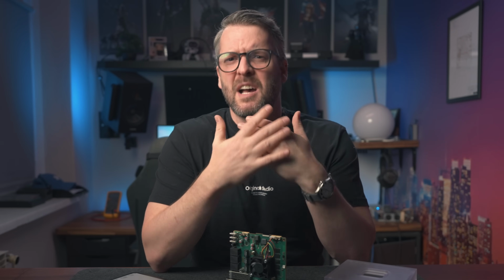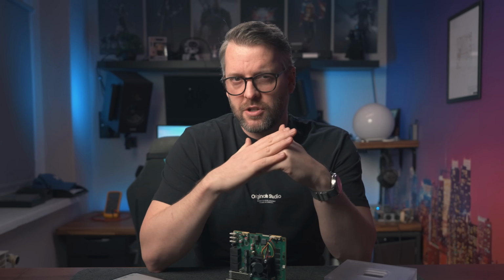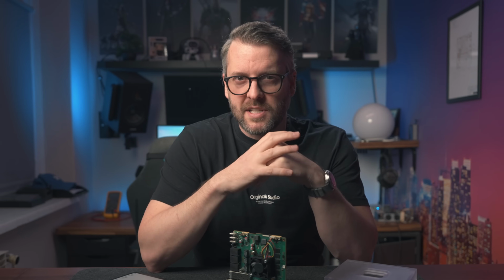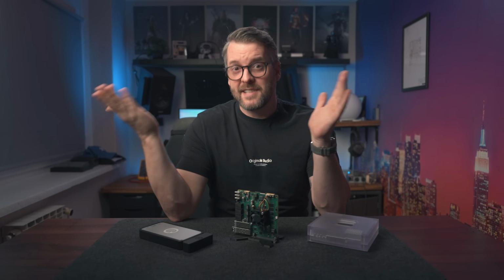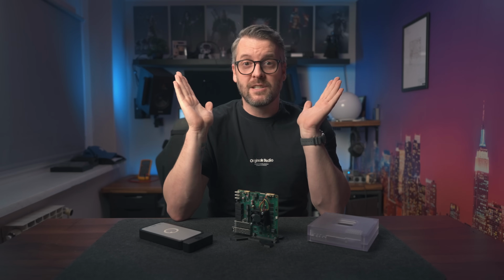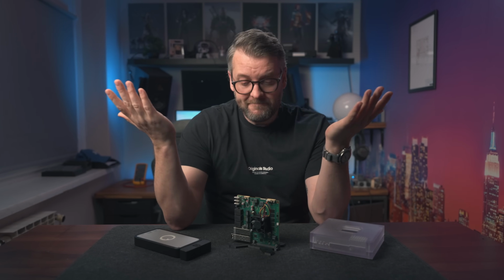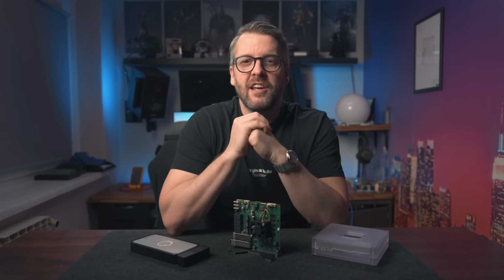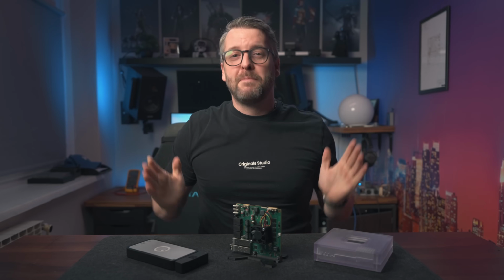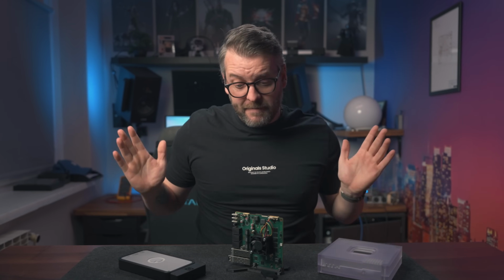But when the CPU is booting up, and keep in mind this is my assumption at this point because it's not actually documented anywhere, I suspect the controller at that point does care about the organization of the drawers in the rack or how the bits are wired to the CPU. And in case it finds anything, it sets this calibration error bit with zero explanation as to where the issue might be. And as to why this behavior is not documented anywhere, ask NXP. We certainly did, multiple times in fact. And multiple times we were offered their $200 per hour support package. It is what it is.